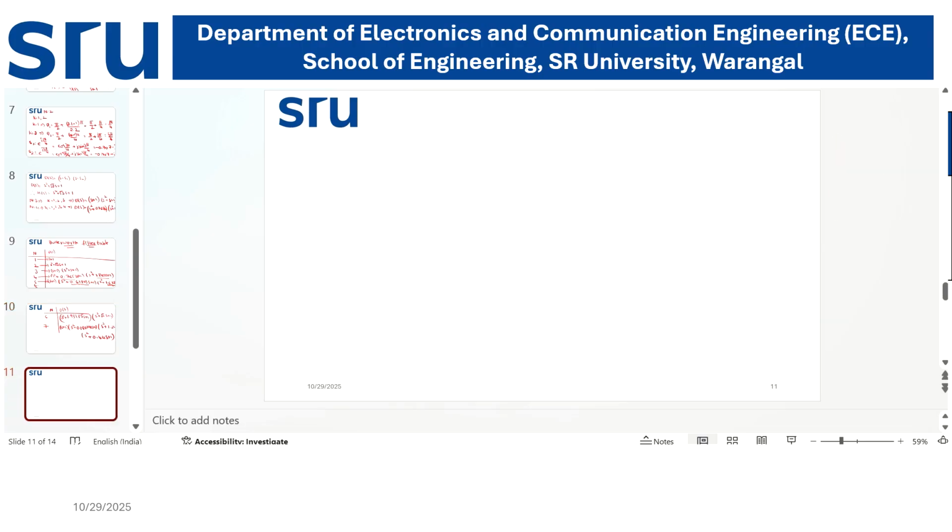Now we have derived 3 steps. Now the fourth step: in general the cutoff frequency will not be equal to 1. It is normalized if it is equal to 1. But to find the unnormalized cutoff frequency, and thereby the unnormalized transfer function, the cutoff frequency formula can be in terms of the stop band frequency, or we can find it using the pass band frequency.